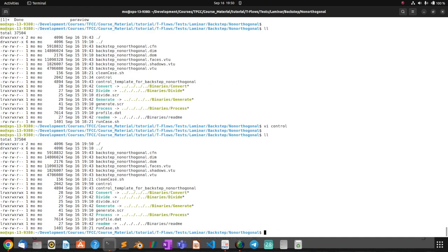progression of the solution. In order to run the case, as we did with the generate, you can go ahead and click process.process. And if you want to follow up on the solution or dump the solution log into a file, you can use this symbol here, bigger than, then you say log, or let's say out results, let's call it serial case. And I put the and sign again, so I can make the process run in the background, and I can always view what's happening when I want to.